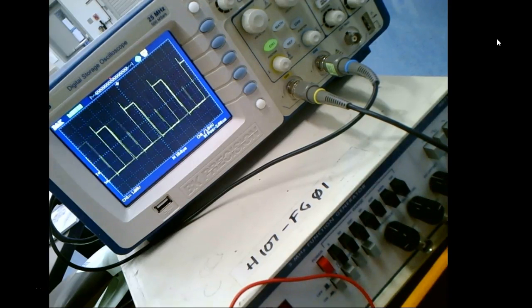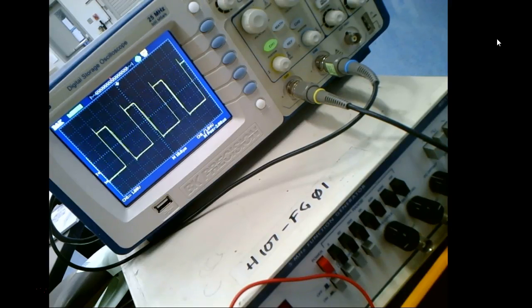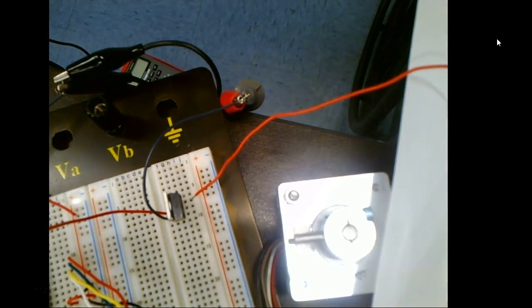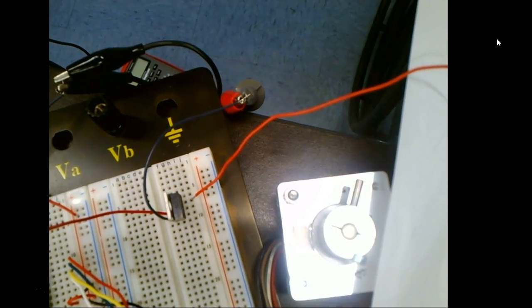If you came up here and felt this transistor that I'm running with, it's not getting hot at all. If I did it with a resistor, when I slowed it down, the resistor would get real hot, right? What's happening is this transistor is either off or on. We turn it wide open, and it drops very little voltage, which means it's going to create very little power, right? I squared R. And when I turn it off, the transistor's off and there's no power at all, right? You understand? What's nice about this is we can switch this thing off and on real fast.